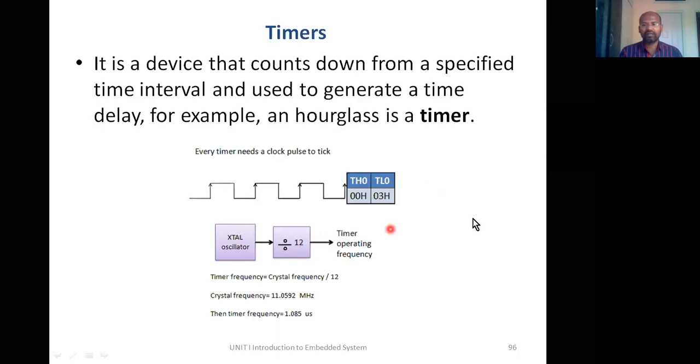For that, we have control registers. Every peripheral, and the timer is one peripheral, comes with some control registers and some general purpose registers, right? By writing 1s or 0s in some locations, you can change the division value. You can change the division to 8 or 12 or 256 or something like that. For that, you need to refer to the data sheets. In this course, we use microcontrollers, and there we will talk about timers in a detailed way. That is timers for now.